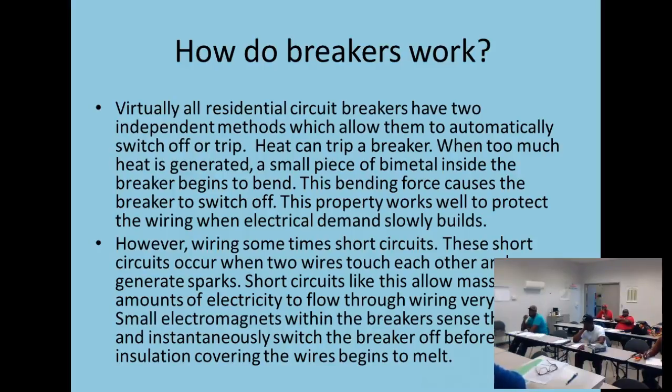Now, if you don't, you may want to make sure it's set in the on position. Okay? Now, if it's in the on position and you don't have power, what you want to do is cut it off. You want to disconnect the load side, all the load wire. Cut it back on and test to see if you have voltage coming out the load side, right?